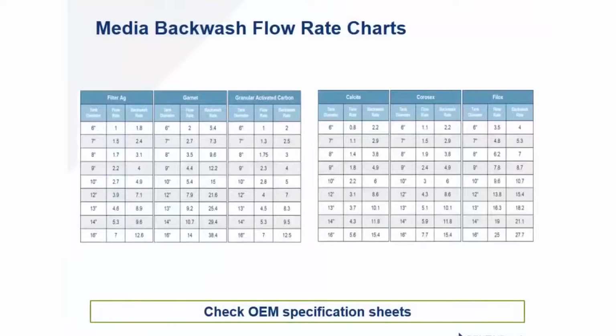Getting a question coming in here. To confirm, warm water temp allows for better lift but requires longer backwash time? No, just the opposite there. Warm water allows for less lift.